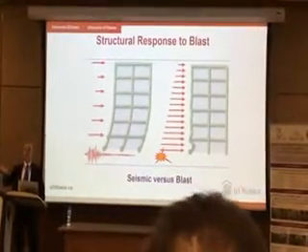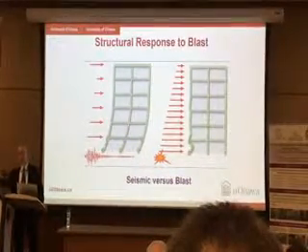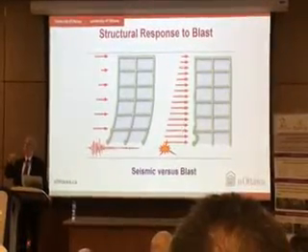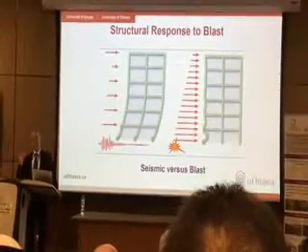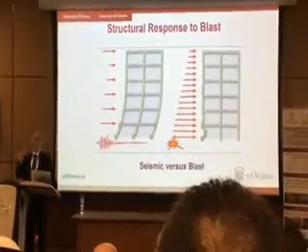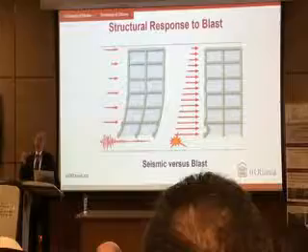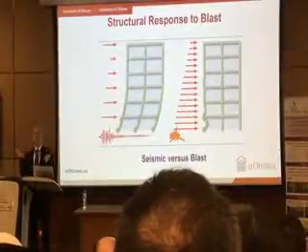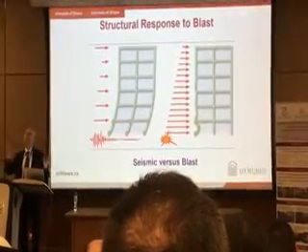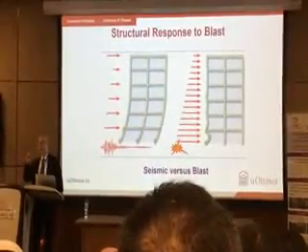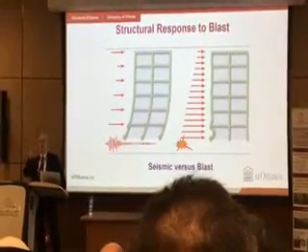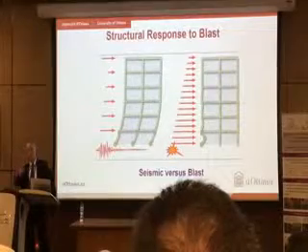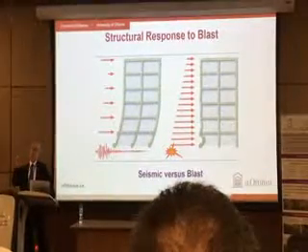So when ground shakes, you induce accelerations. Mass of the building, which usually concentrates at floor levels, causes internal inertia forces. So in earthquakes, forces are internally generated inertia forces, and those forces are resisted by the entire building because mass is distributed, the whole building responds to it. And as you know, there's a very delicate relationship between the frequency of the structure and frequency of excitation, right?